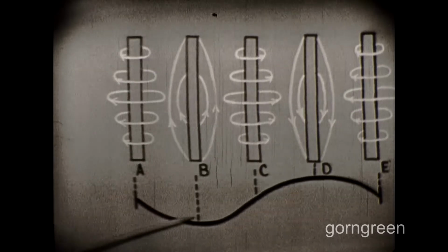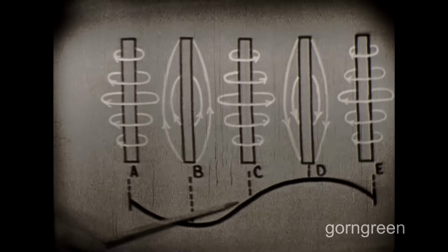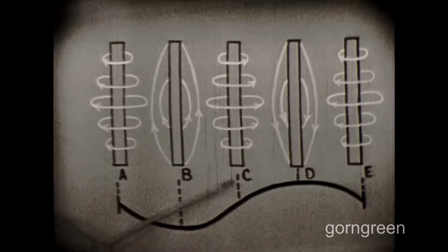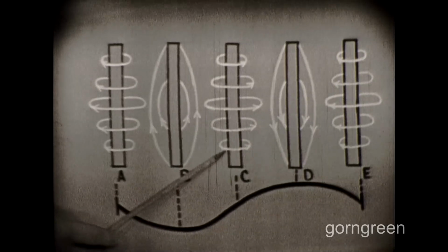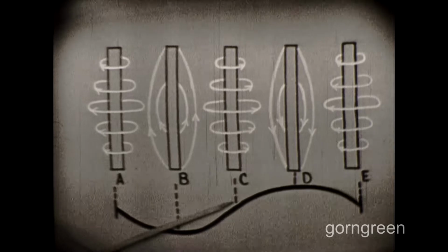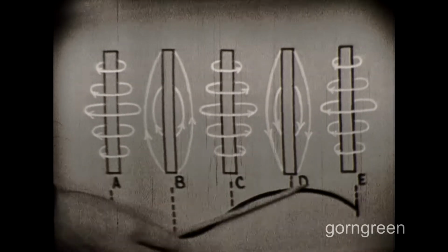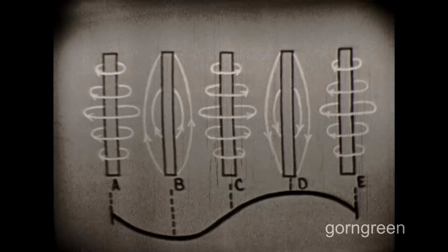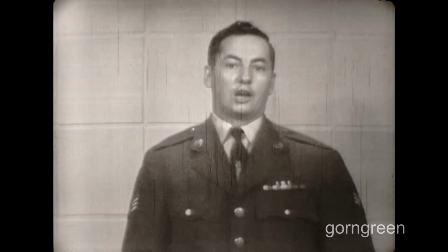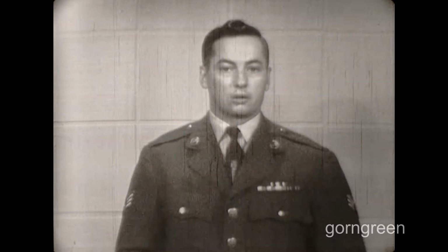Now, still at point B, the current starts to flow in the opposite direction. The electrostatic field starts to collapse, and the magnetic field is of maximum intensity again at point C. Current flow is again 0. This cycle repeats itself during the positive alternation of current flow. From this, you can see that the electrostatic and magnetic fields are developed 90 degrees out of phase with each other.